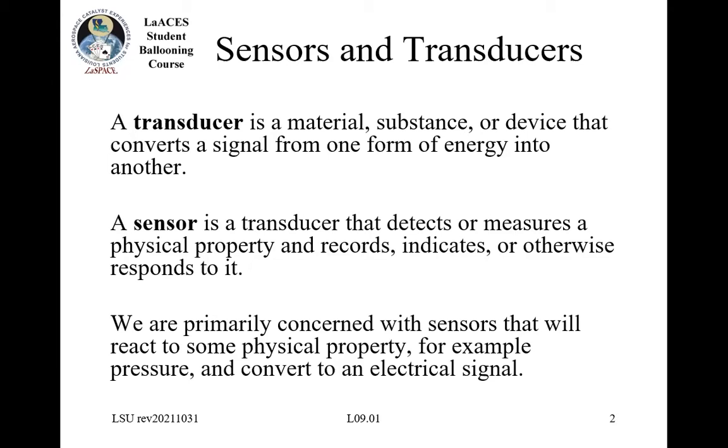So we'll refer to things as transducers or sensors. Honestly, more often you will use the term sensor just because that's what everyone's used to. But in this context, a transducer is anything that will convert a signal from one form of energy to another. So, obviously in this case, we're going to be talking about turning physical signals into electrical signals primarily, but it could also be the reverse, where you're taking an electrical signal and converting it into, say, a heat signal, a heater in that case.